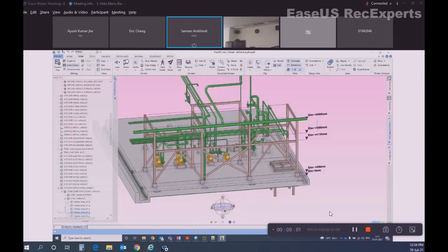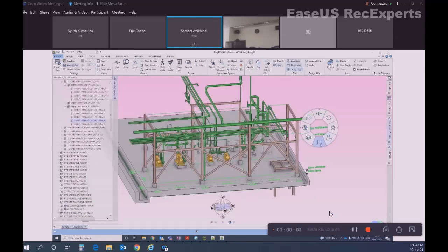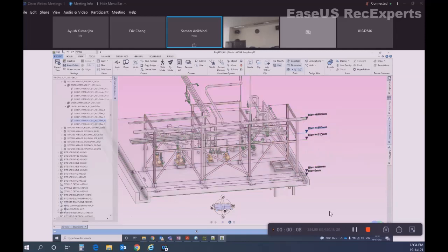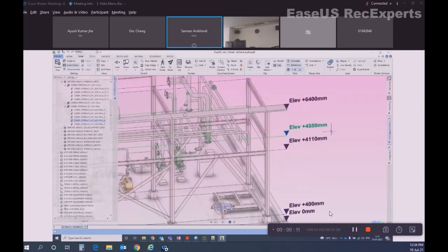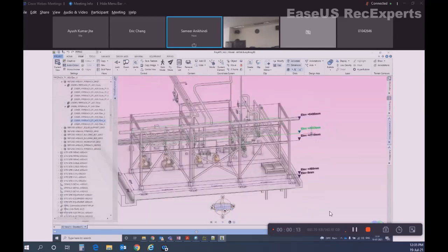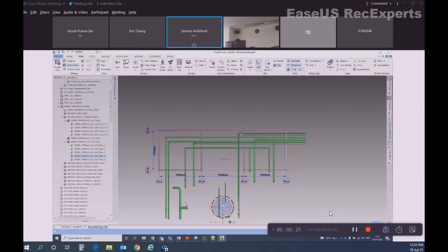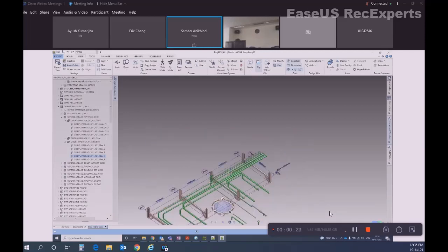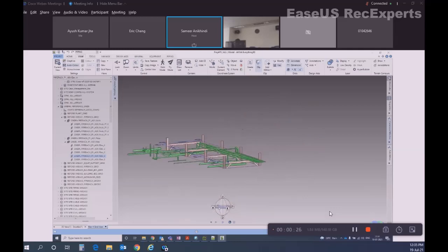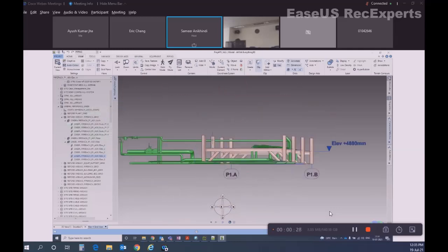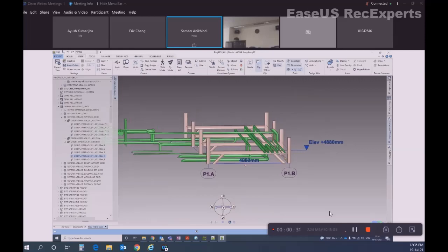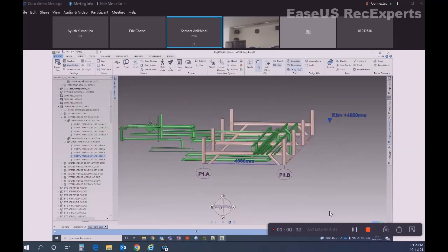Select again, for example, I want to analyze this tier. I select this grid plane and this 4800 plane is selected. While this is selected, you have to go to grid plane view and see. Automatically, the direction of the grid plane is also set, with 100 mm above and 100 mm below. If you want to increase the elevation, you can increase it. See, this is a clipped view. It opens elevation 4 grid view.